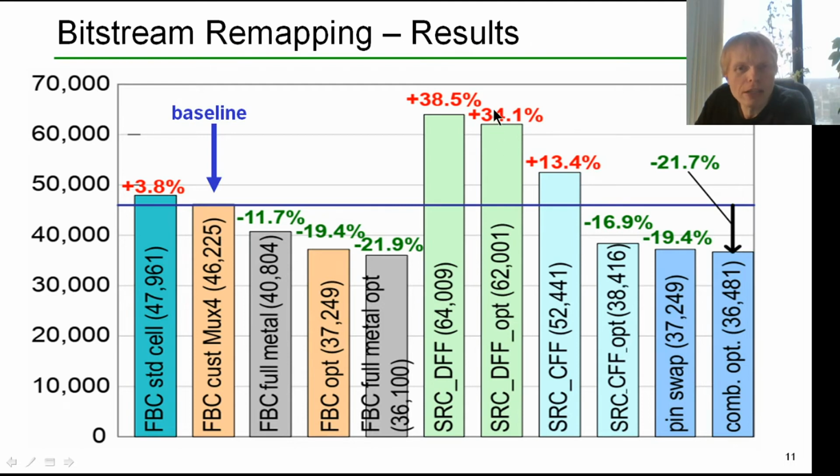The reason why it's not more is very simple: the D flip-flops are so big, they force the tile to be big, so it gives you a lot of space for getting the routing implemented, and by definition such a design is much less congested.